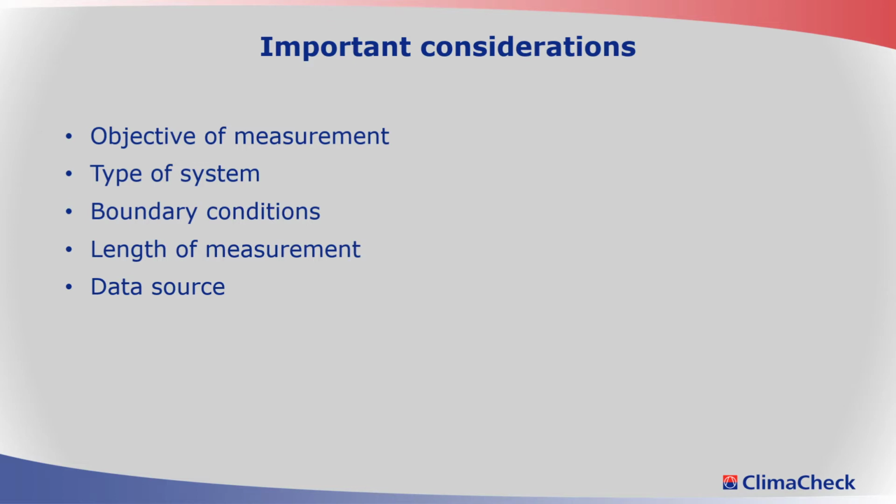If it's a heat pump, then we would like to measure during winter. We would maybe like to know how it is operating during the coldest days, or maybe how it is operating during the fall when it's not so cold outside. So these are two different measurements, and this will dictate how long we would like to do the measurement.